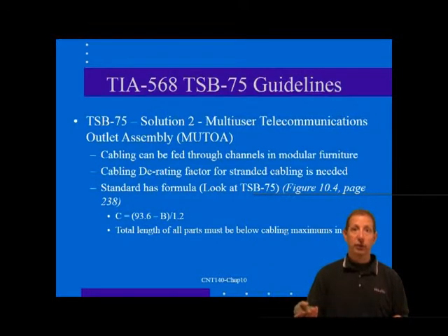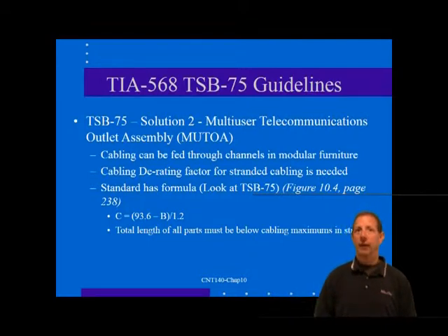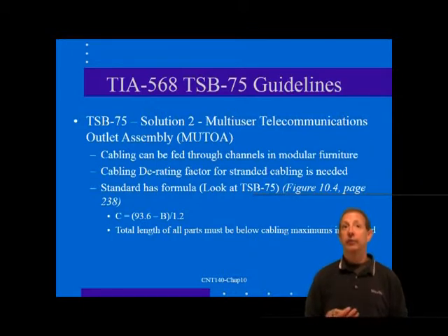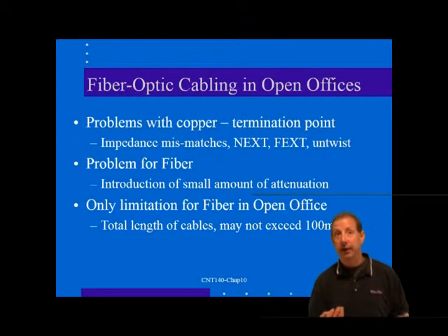In the end, you really must check the entire channel link, as that is the ultimate connection path on which the high-speed network must operate. If equipment and patch cords are not yet installed in the TC, you might consider testing the channel using the actual extended user cord and the 5-meter maximum equipment patch cord.